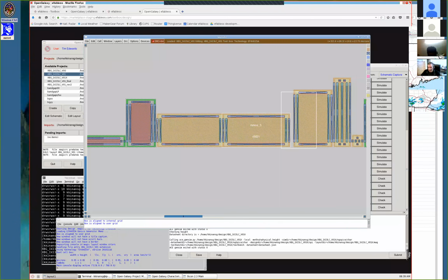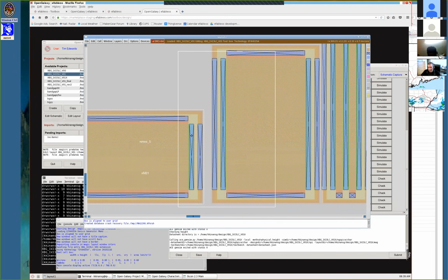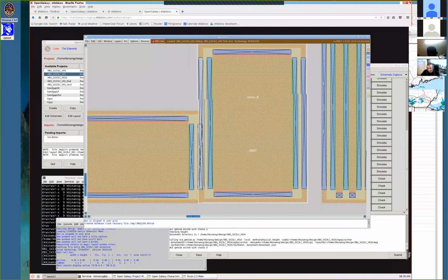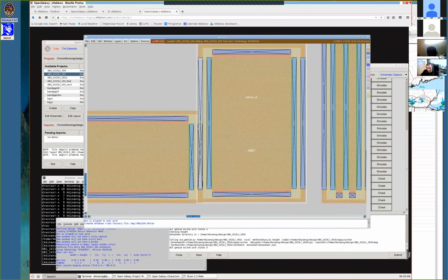Because contacts have to overlap exactly, if I have something like this where the cell width is different than it is over here, then if I try to do the same trick there where I overlap the guard ring, then I can line it up at the bottom, but I still have a DRC error. Why? Because this guard ring contact does not match this guard ring contact, and that leaves the possibility that the contact cuts don't align and would create a DRC error in the final mask.